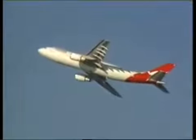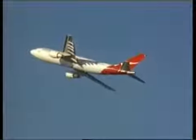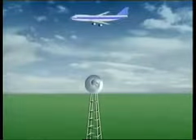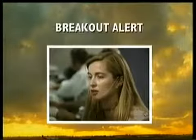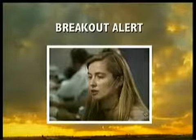Unlike a missed approach, a breakout alert instruction can include a descending turn or a climbing turn. In the event of a descending breakout, the pilot is not expected to descend at more than 1,000 feet per minute, and you will not be assigned a level below the minimum vectoring altitude. A breakout maneuver requirement will always be prefaced by the phrase breakout alert.